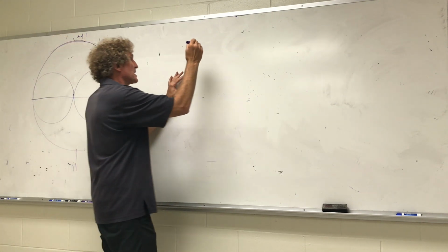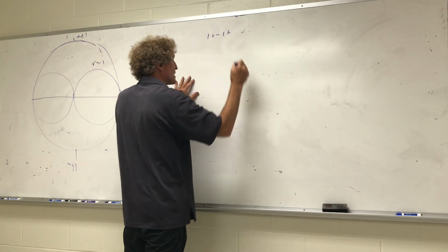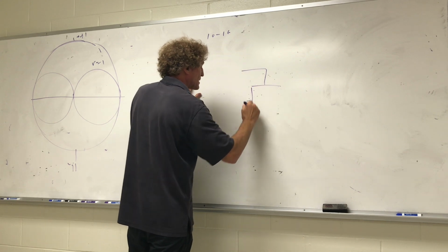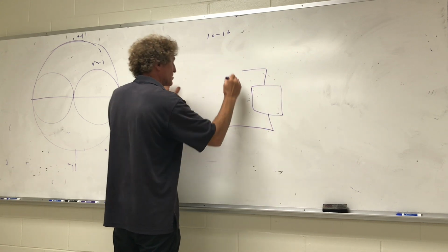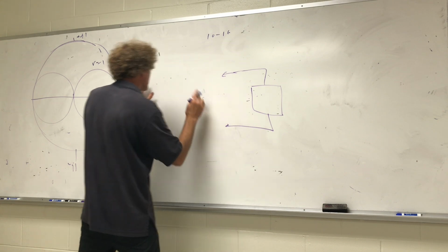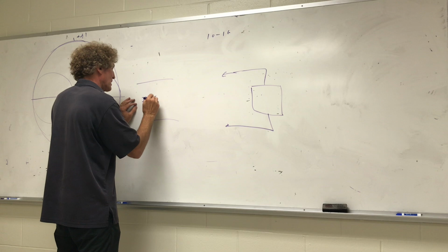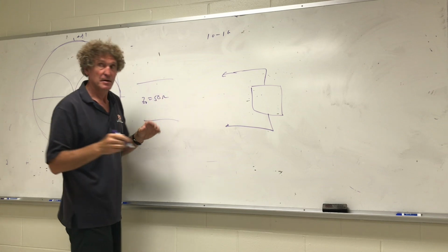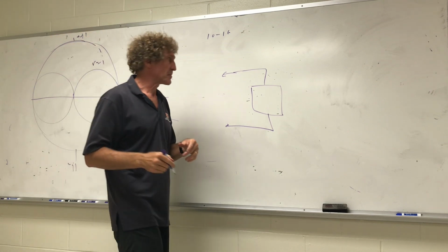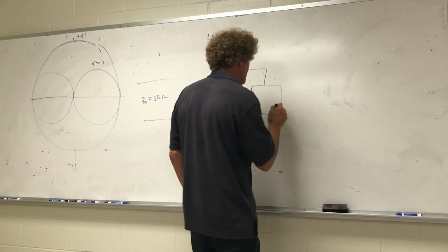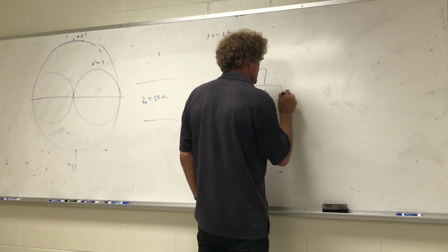All right, this is 10.16, correct? Yes. And we can outline all of them very quickly. And they want an L section, right? What's the characteristic impedance? I assume 50. Yeah, that's microwaves, typical microwave stuff. And what is ZL? 20 plus J50.